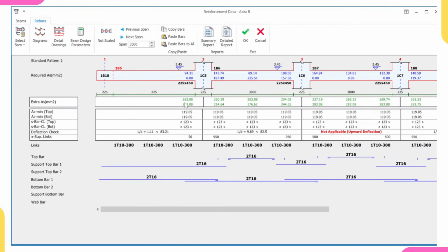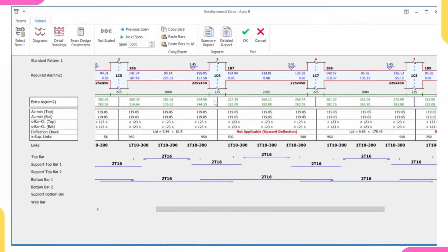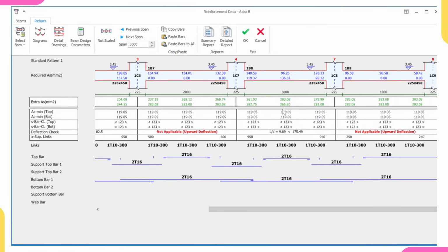And also the yield strength that you are telling us is 460, it might no longer be 460, it might be 420, 430, or even 410. So to counter that, I say make sure that this area of steel provided, that's the extra area of steel provided, is not less than 100. So ensure that in your design. So here you are not having any of them less than 100. Please ensure that, to avoid building collapse, because these are some of the things that cause building collapse.